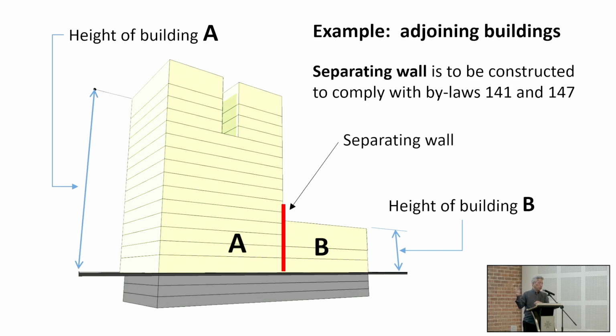But of course, if you do decide to break up the lot, subdivide it into two legal titles, and sell it to two separate owners, go ahead. You already have a separating wall, but not so quick. Why? Because your separating wall between these two buildings was designed at the same time by the same architect, isn't it? It's probably using the same fire systems. So you have all the sprinkler pipes and everything crossing the wall. But once you divide it into two separate ownerships, that will have to be turned into a party wall.